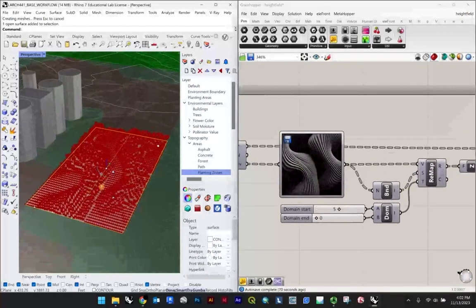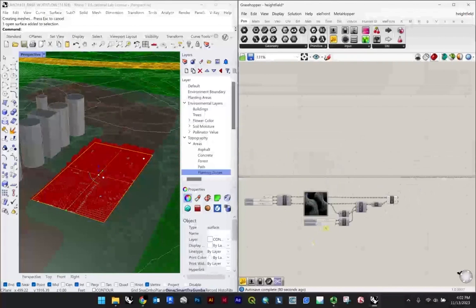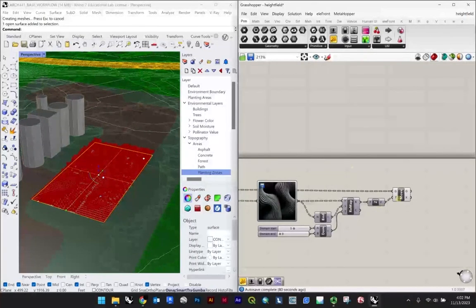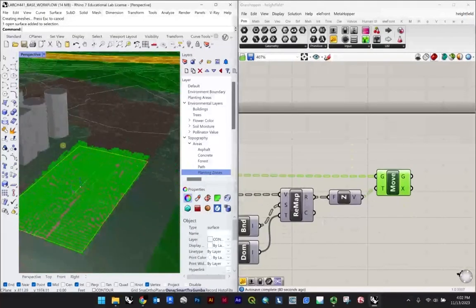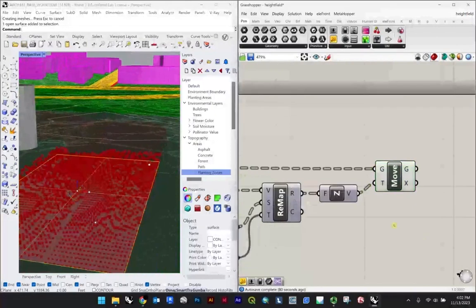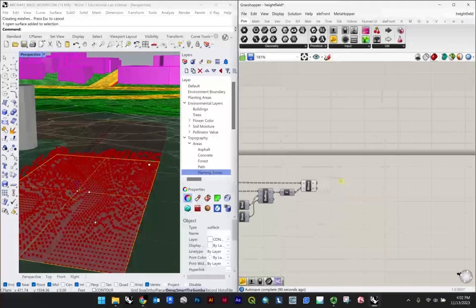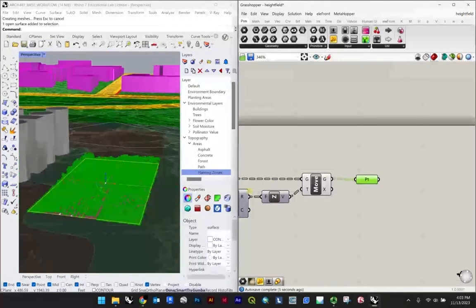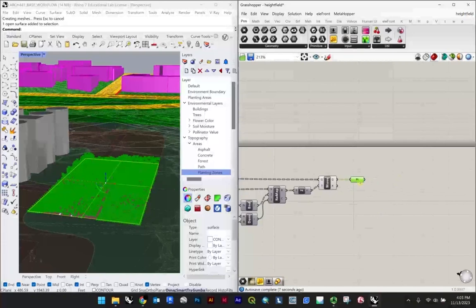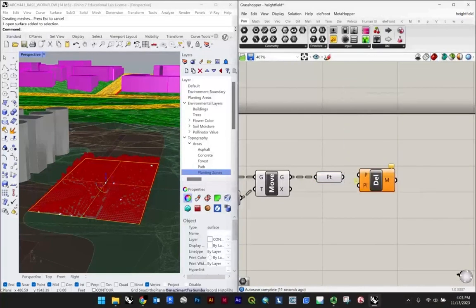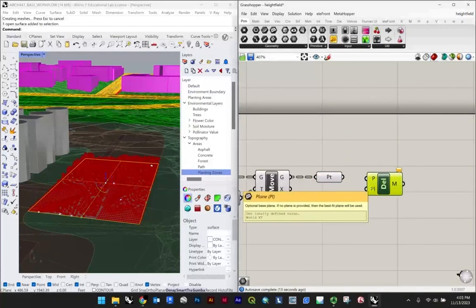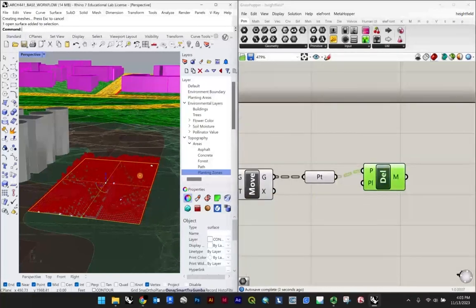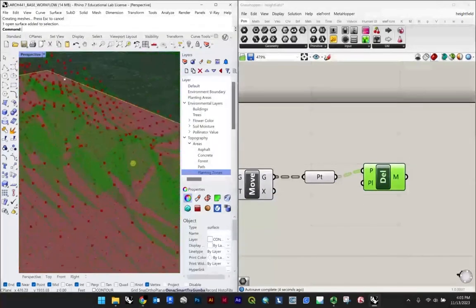We can test both in the video, but the one thing about this script at the moment is our outputs are points. So in this case, our output geometry here is a point, right? So we can do geometry to point. And what we would want to do from here very likely is a Delaunay mesh function. So Delaunay mesh goes in here. When we preview that, right now it doesn't look very good, right?